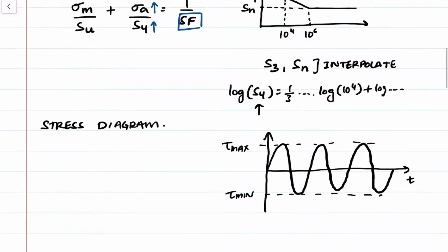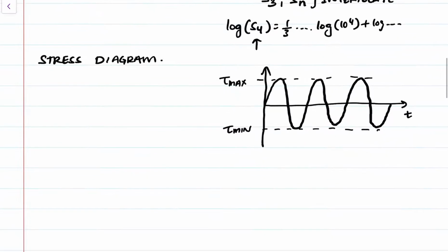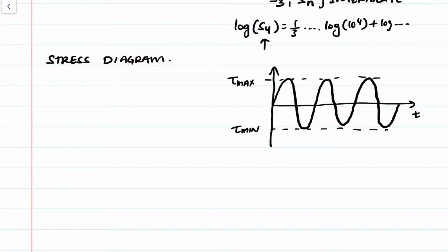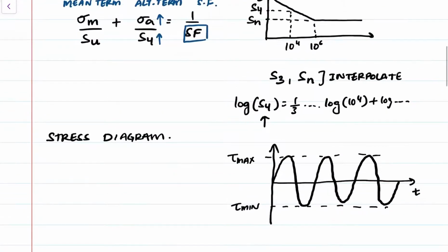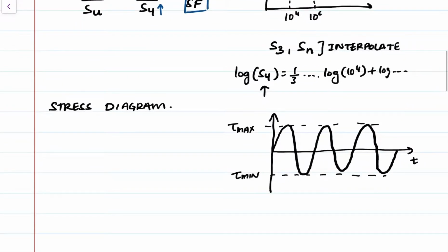And you can already tell that tau max is just going to be your 16T over pi d cubed because you have a rounded shaft and it's only due to torque. So what we need to do now for the first part, like I said, I start with the equation. So I'm going to rewrite that equation in terms of tau.